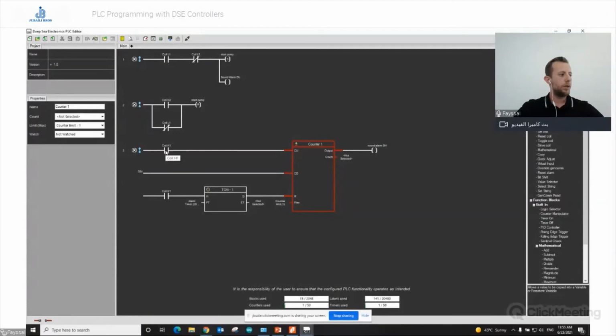So we have a coil, our fuel level is high, the counter goes up by 1, we've reached the maximum limit, the output is true, it will sound alarm bulk tank high. So this will keep on running. If I leave this as it is right now, the alarm will never shut down unless we reset this counter. So I need something to reset this counter.